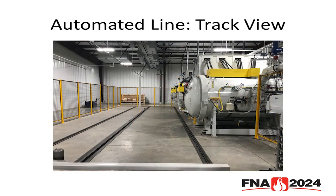This is just a side view here. You can kind of see the tracks in the floor. That's how the automatic loader operates, going up and down the tracks. There's proximity switches along the tracks. They're going to tell the doors when the cart is in position, when it should open the door, when it's clear of the door so that it can open, and that sort of thing, so they know where the position of the load cart is.